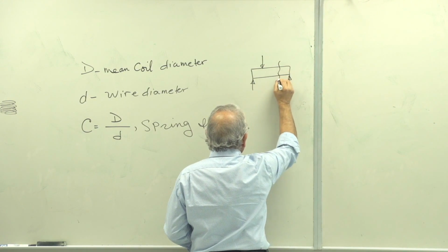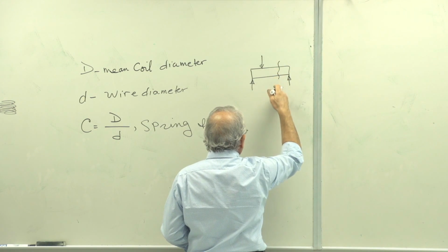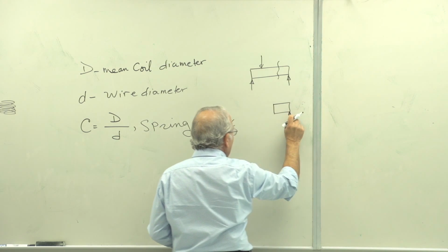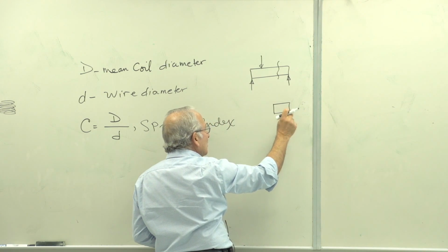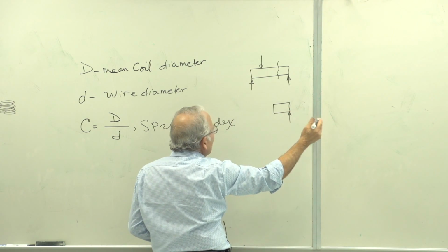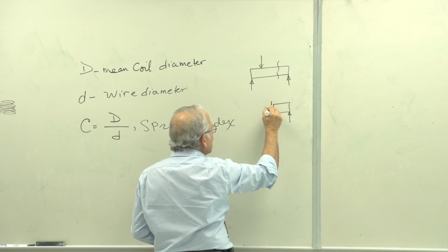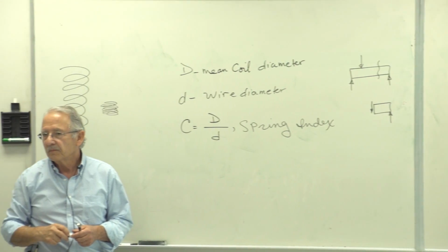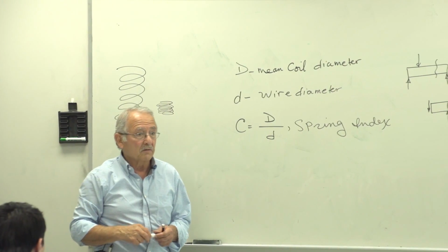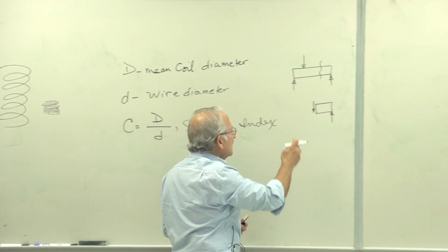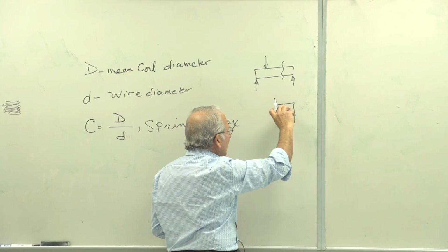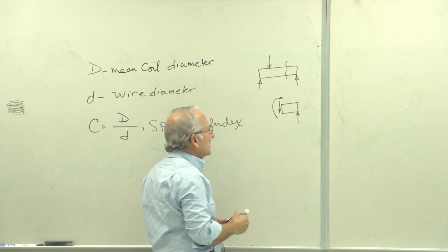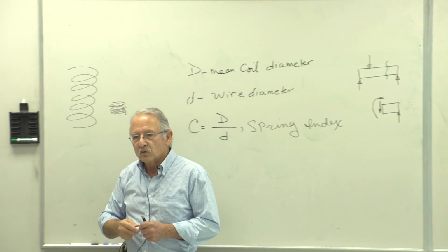You want to find what the load is here. You make a cut. And you say that in order for this right-hand part to be in equilibrium, the only way that is possible is that there must be a force there equal to it. There is no other place for that force to exist. And of course, then these two create a counterclockwise couple. So you say, well, it's got to be a clockwise couple in here as well. And that will give you equilibrium.